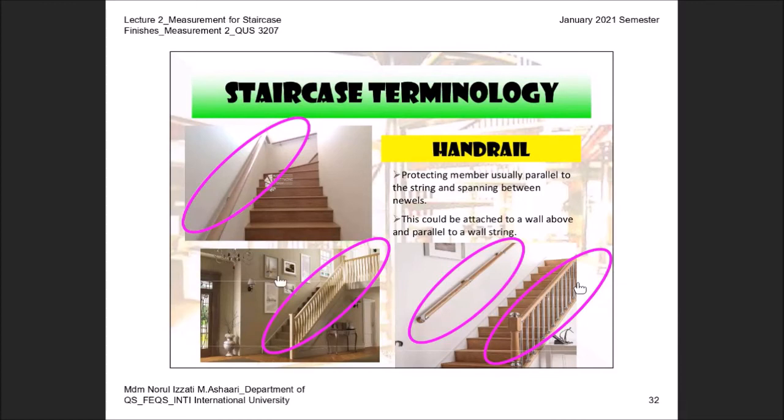And this is the design where you don't see any handrail bracket because the handrail is only at one side. Where you have the staircase that is covered with both sides covered with the brick wall, normally one side must be installed with the handrail, where this handrail is installed with the handrail bracket. Okay, if you have this kind of design, normally we don't have any balustrade.